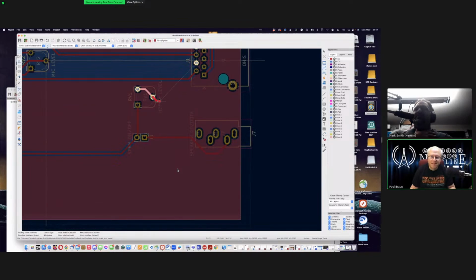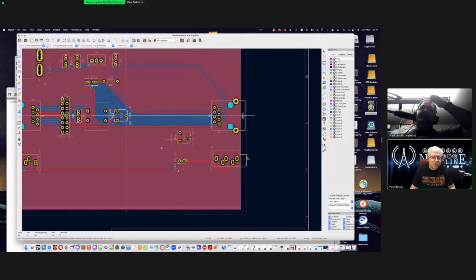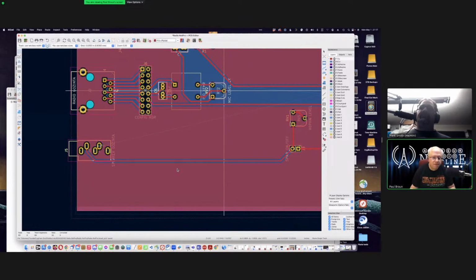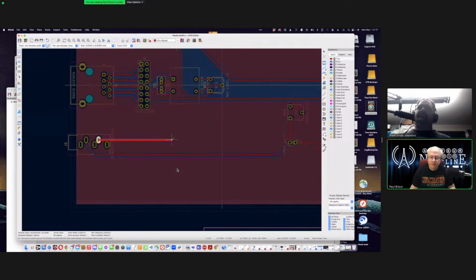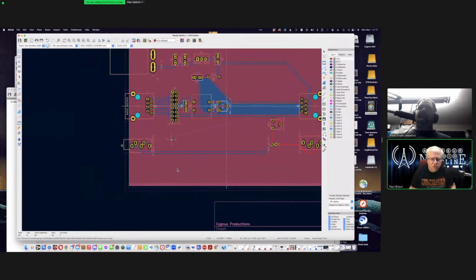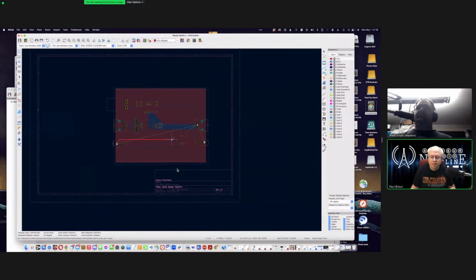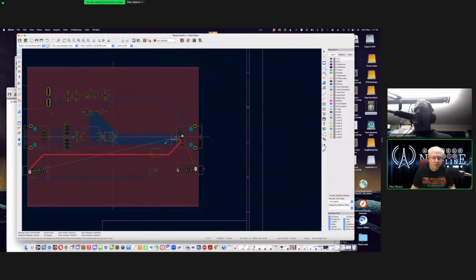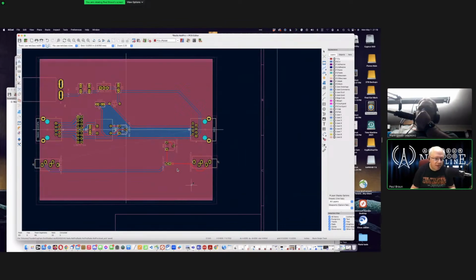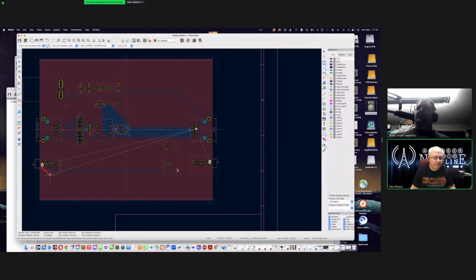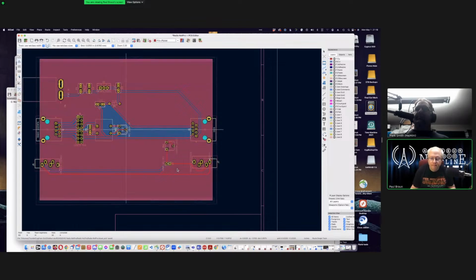Right in the middle. I would recommend going to the bottom layer. Okay. So then let's do this first. That's not going anywhere. Which one am I going to? This one? Yeah. I would go underneath, on the bottom layer. Yeah. No. Okay. Down here. Yes, exactly. And then go across to the 3.5 millimeter, and then from there you can go up. You'll still have to go on the bottom layer to get around to some of those things, but at least it's shorter.